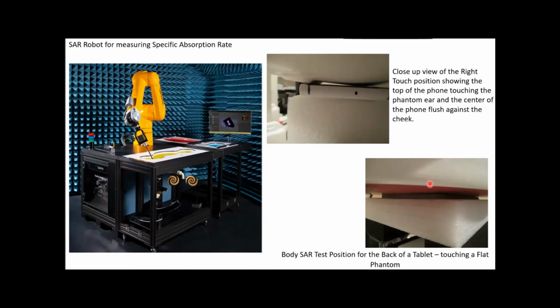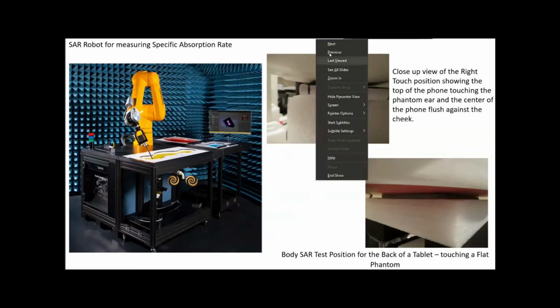We're measuring the SAR at this point here, but here the antenna is actually at the point where we want to measure. On a phone, generally we're transmitting at the bottom. We're transmitting down here for the phone, but the actual SAR measurement is actually by the ear. So there's a big distance here to here. That's why phones can sometimes get away with having lower SAR values, because really the transmitter is at the bottom of the phone, not the top where the SAR is actually measured.